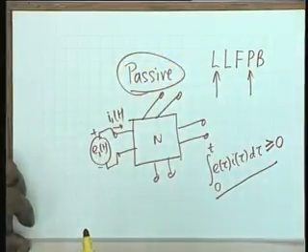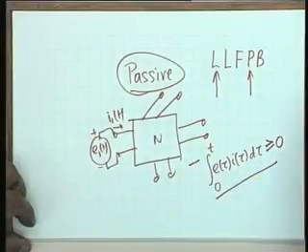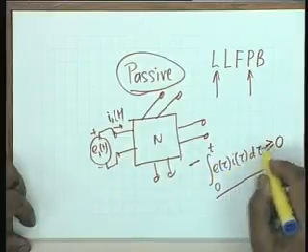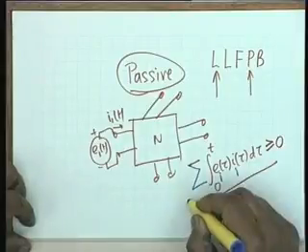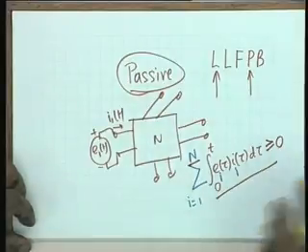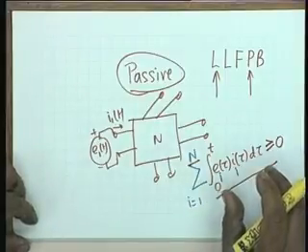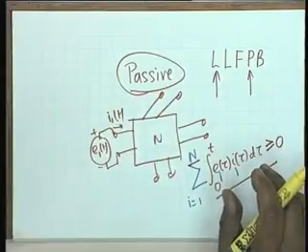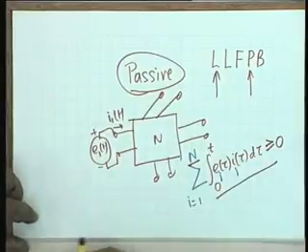It should be the sum over all these ports, all these terminals. Okay, good point. I was waiting for this. This is for one port. So, it should be a summation of E_i(t) I_i(t), i equal to 1 to N. That is the sum of all the energy supplied by all the sources. You have to sum this up over all the ports, and if this qualifies to be non-negative, mind you, the condition is initially the network must be relaxed. Only then this condition can be applied.